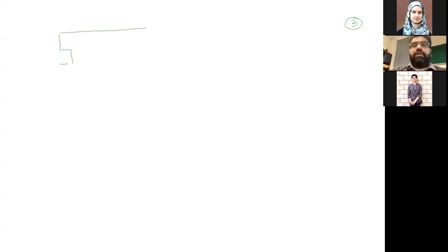So here up we have a PMOS load. Again, this is a PMOS. The PMOS load is going to be shared, so that's why we draw this common node. And when we draw this, here we have our diode connection. On one of the sides, we have a diode connected, and I'm going to explain why we are doing this.